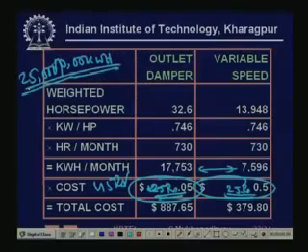So, therefore, people always opted, even if they were not energy efficient, for this damper and valve control kind of techniques. But now with these variable speed drives really becoming robust and cost effective, it makes a lot of sense to acquire variable speed drives for such equipment. Okay.